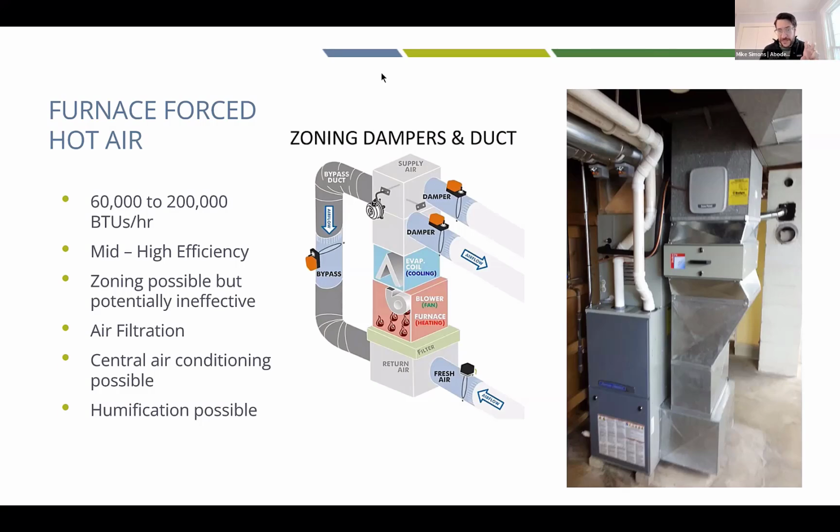Sometimes if it's a mini split style heat pump and you're zoning it, you're going to prevent it from modulating, and it may just run as a single stage equipment, which brings down the efficiency and may slightly bring down the comfort level. But there are third-party zone controls that do play well with mini split heat pumps.